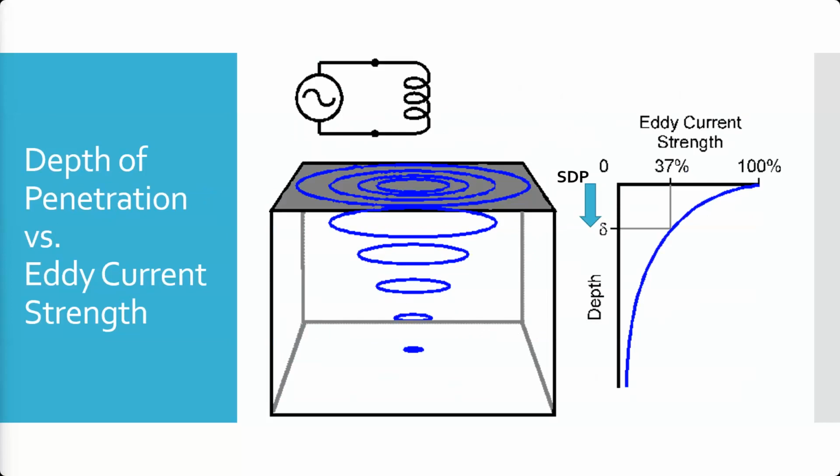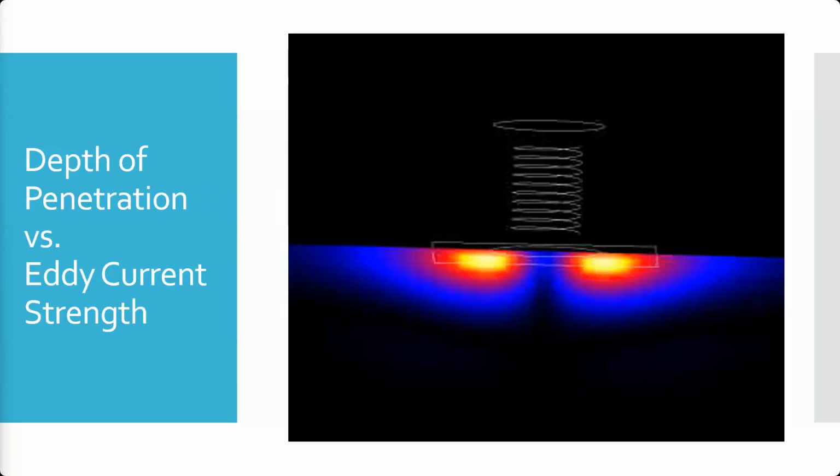They've actually done this, you can use a visual magnetometer to look at how this occurs. So here is the coil, it shows what the coil looks like on a part. And you can see that cone forms. Now, because the coil's circular, you actually get two areas with this coil here, right? So the strongest part is in yellow, and then it drops off to red, eventually blue and purple and black, right? This is looking at that strength of magnetic field.